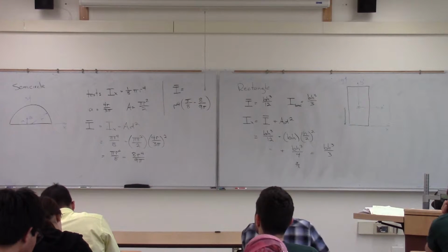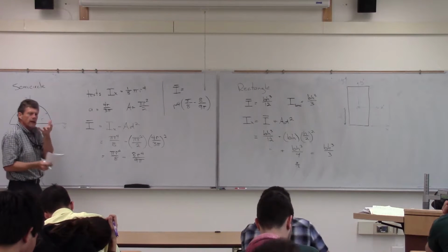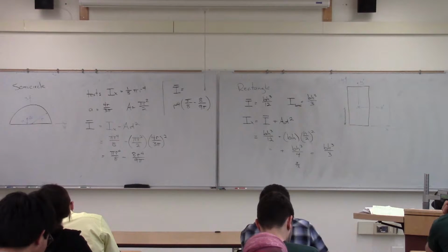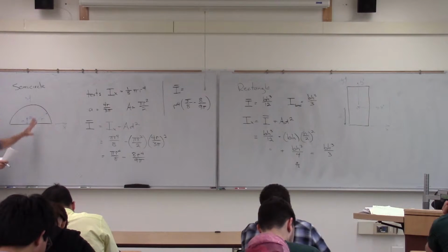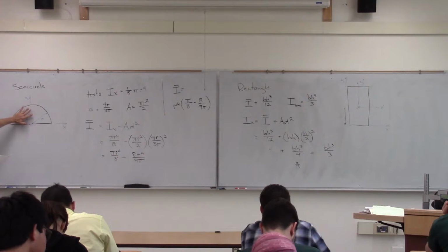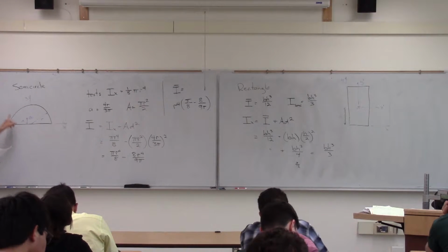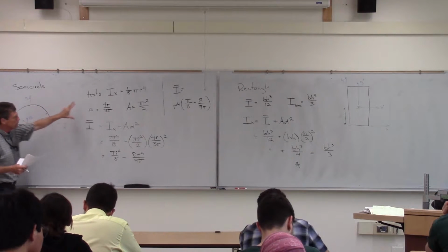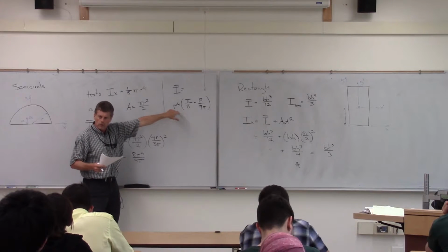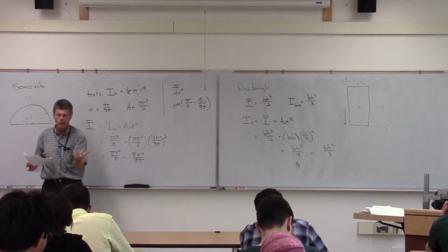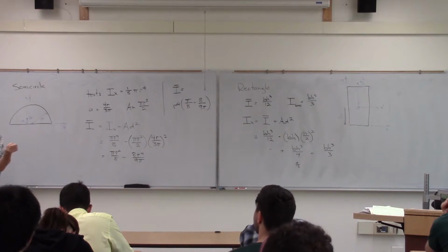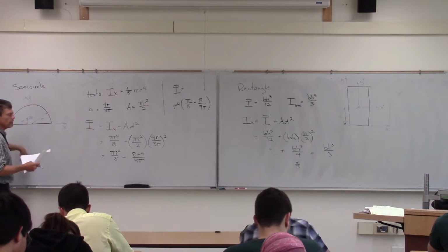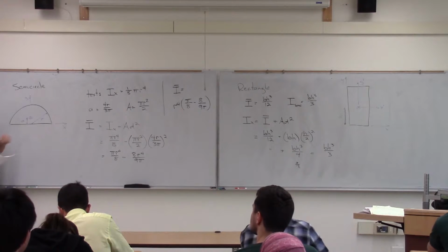And actually you can confirm that because for some reason other statics books give it, while our author doesn't. But again, the point is if you've been given a moment of inertia about some axis, and you're going to be maybe putting this on a composite, there might be the ice cream cone that we did in one of the exams there. We might need to do that. What we can do is simply do a two-step process, use that form 2 to get us the moment of inertia about the centroid of that section, and then finally add it to some other pieces that we need.